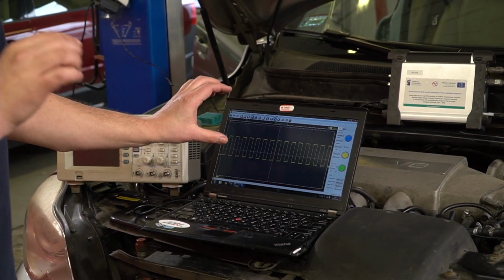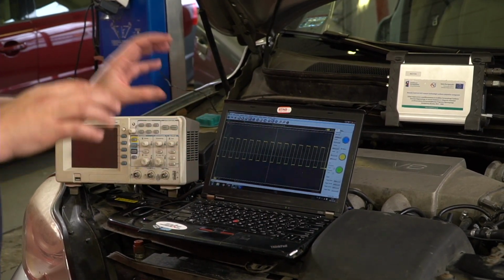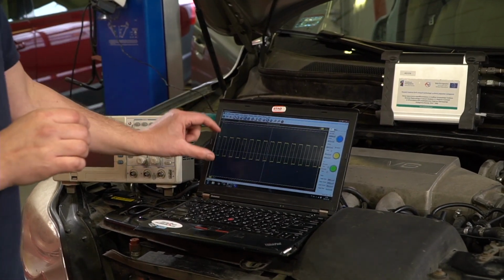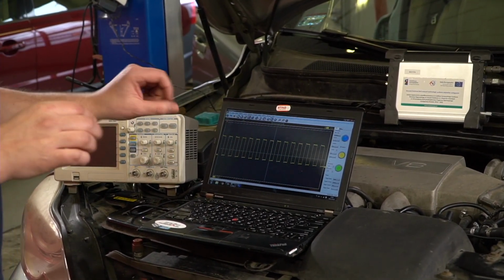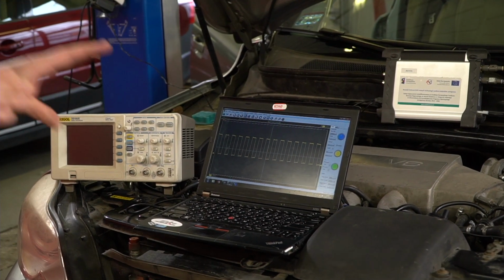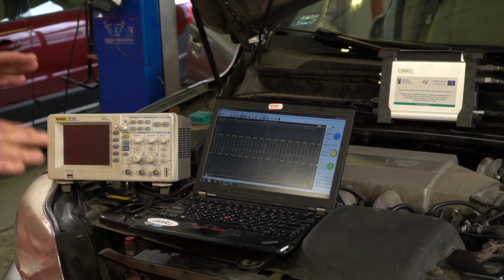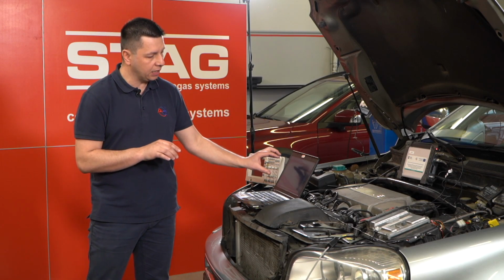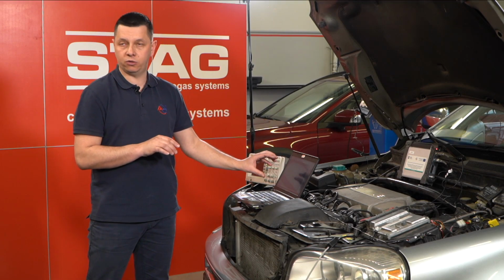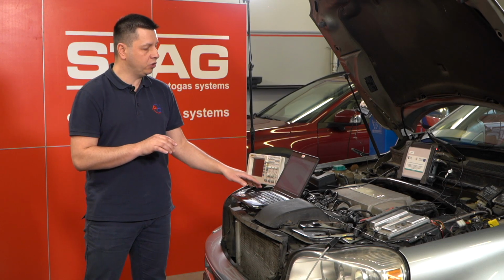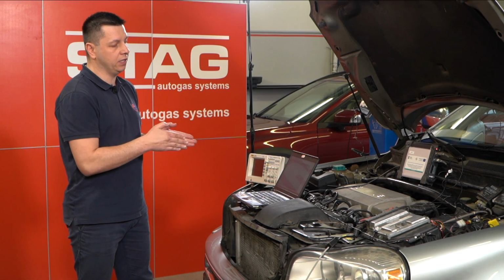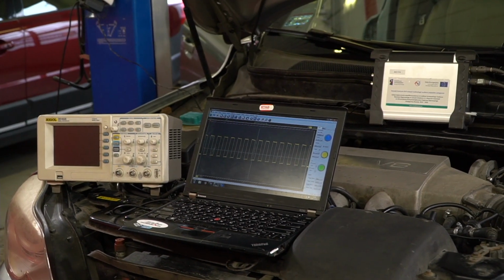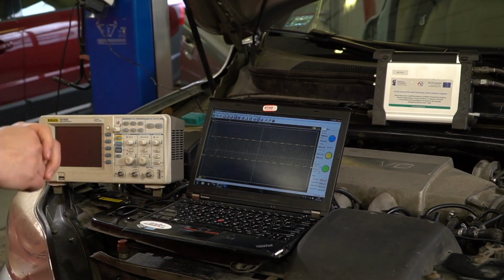This is the problem when you are trying to measure that signal with a typical multimeter. A typical multimeter is measuring the amplitude of the signal. So in the multimeter, even if you are changing the RPM or load of the engine, the amplitude of this fuel pump signal will not change. Only the width of the impulse will be changing. This is the main problem. That's why you need to use an oscilloscope.